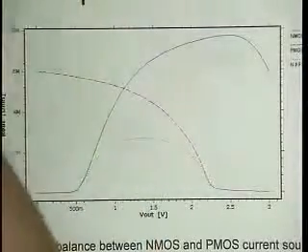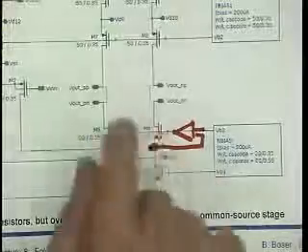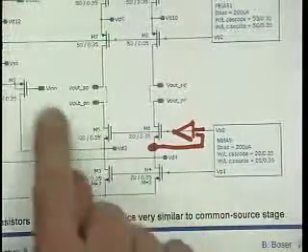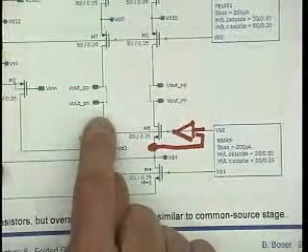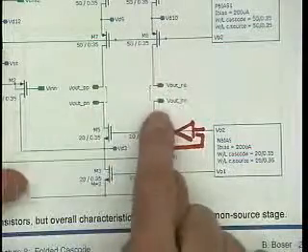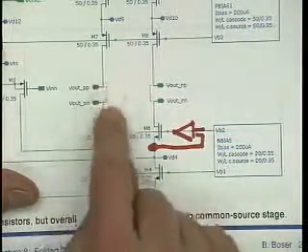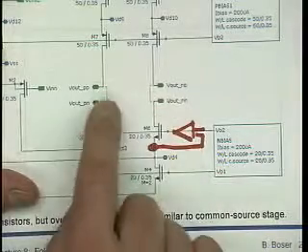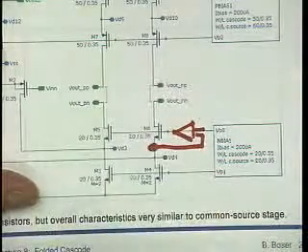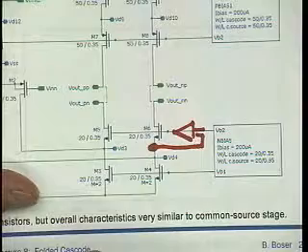That's why, if you look, you don't need to change the zoom, I put my schematic in such a bizarre way. I do not short, right? I mean, this is the output of my amplifier. I do not just tie these together, but I actually bring out four individual terminals of my amplifier.